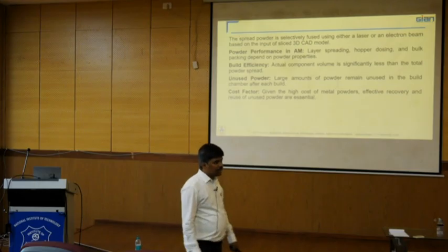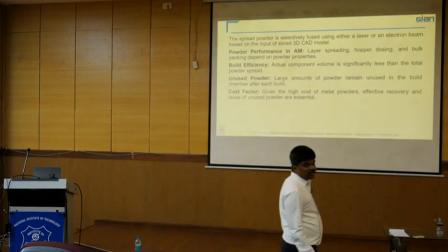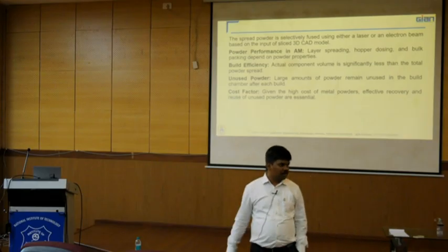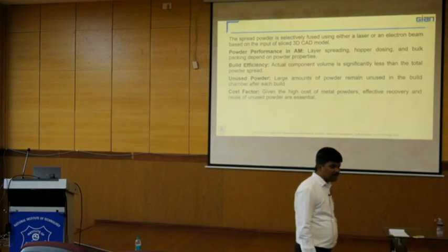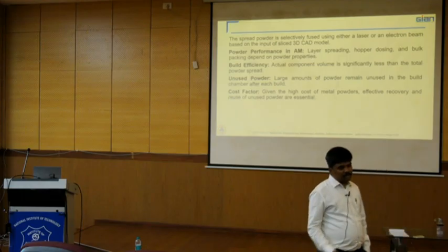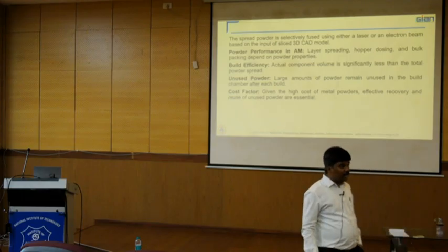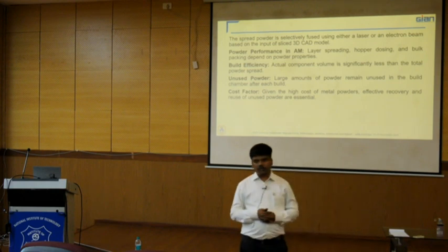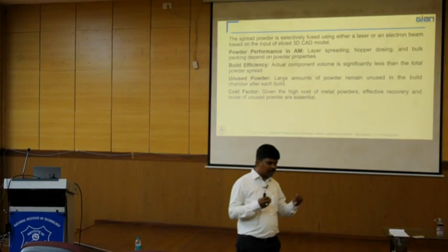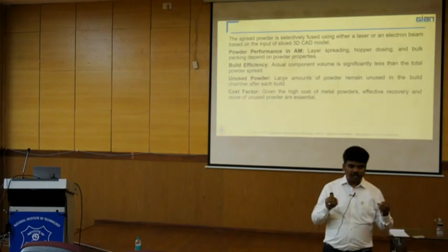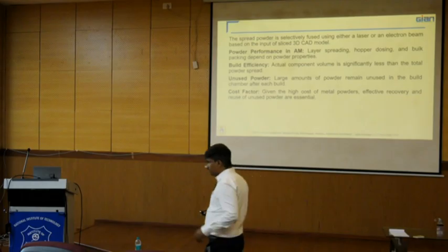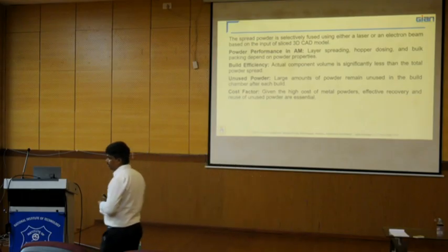We cannot, because it may change the surface properties because of oxidation, or change the thermal properties. There is a slight heat absorption by the surrounding media, or reaction with gases during melting, and also maybe agglomeration in the surrounding powder particles, or satellites sticking onto the surrounding powder particles because of the multiple ejections from the solidification and melting. With all these criteria, we need to think of how to use unused powder particles from the build platform.